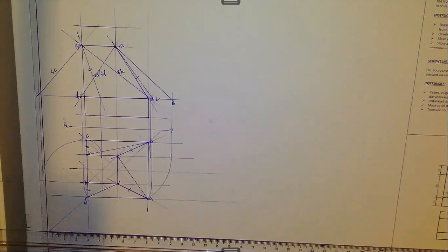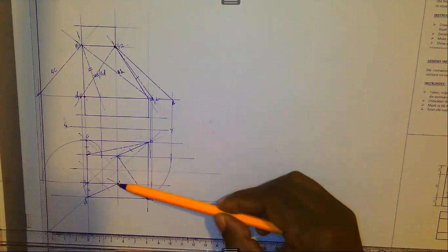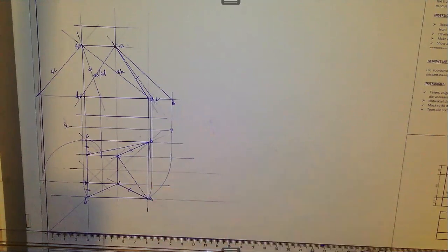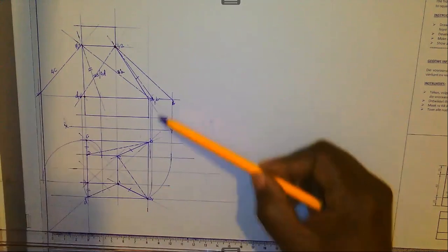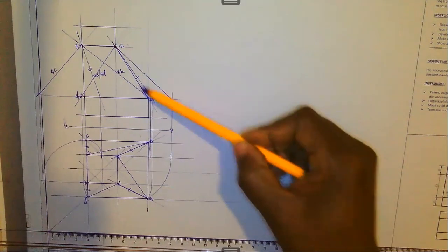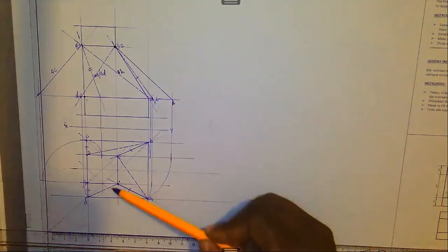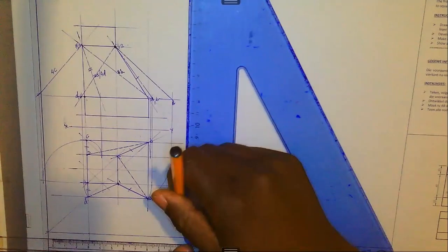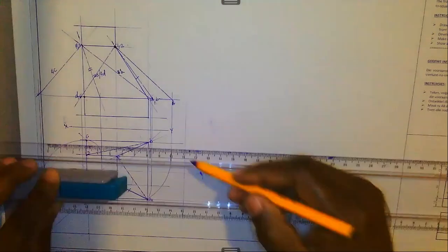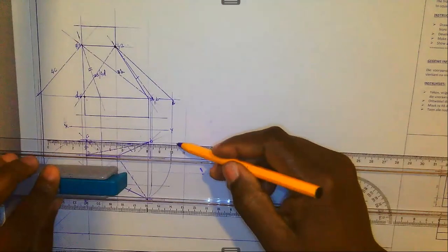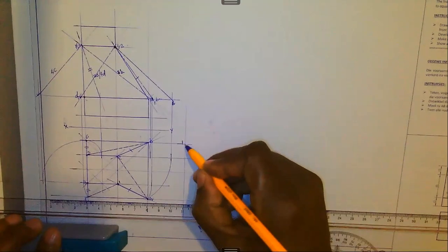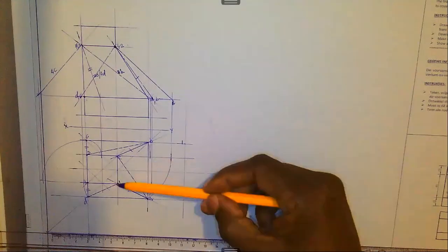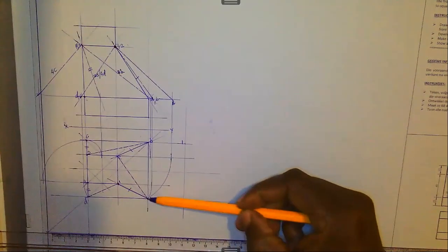We are told that this should be our seam line. If we take that, you'll find that when we stood there, remember, we stood at this point and we were able to describe, you'll find that this now is the true length of 1 to 8. Now, what I would urge you to do is draw a faint line like that, then mark a point, let me start here, and say this is point 1. But from point 1, you need point A, which should be taken from the true length.